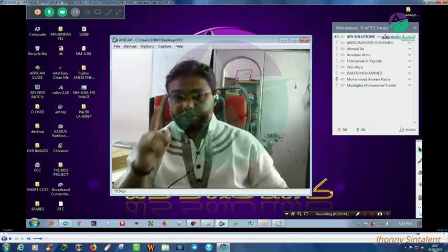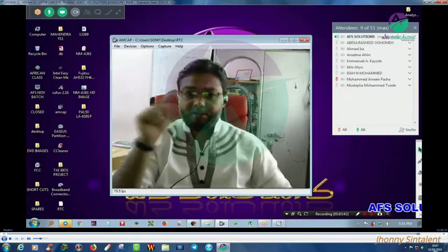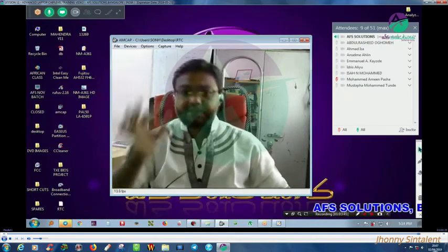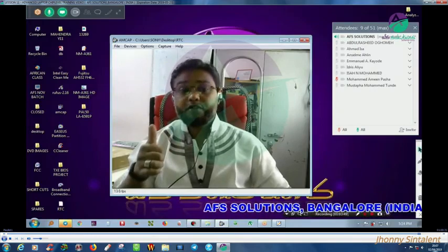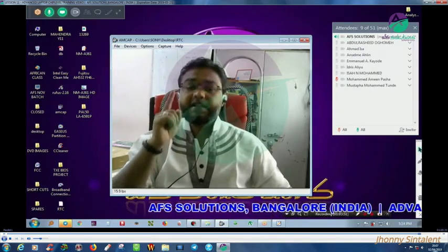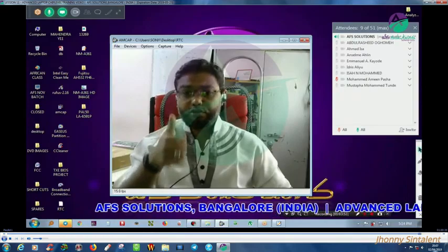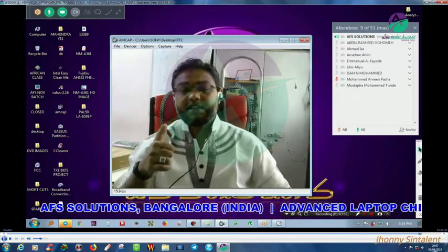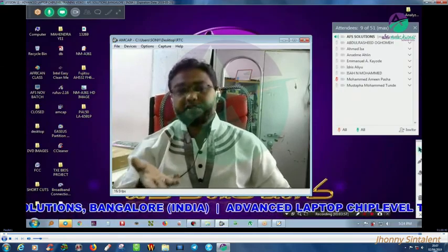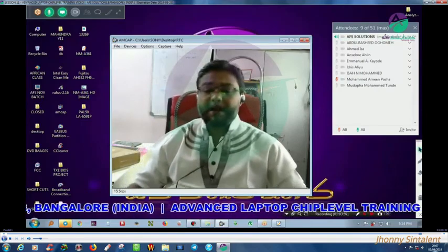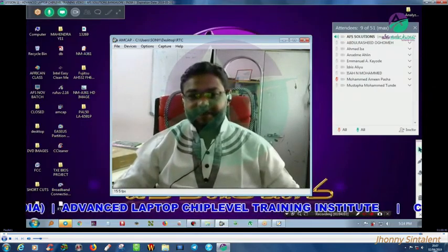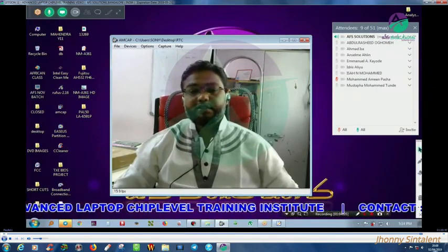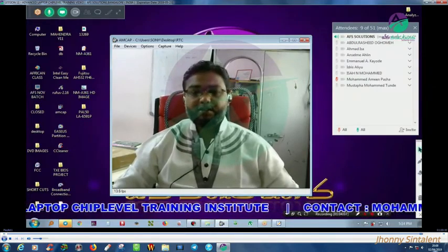Third, what did I tell you? There should be communication between the battery and the IO controller. That means my data pulse, clock pulse, and my temperature pulse. Fourth, my battery cells also should have good health. If my battery itself is not healthy, then what is the use? So you have to test with a working battery also.